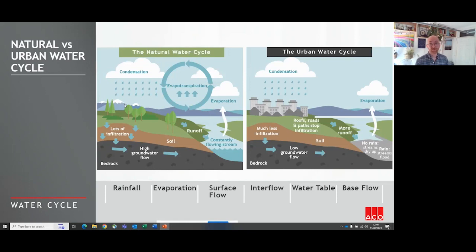Then from the drainage system, it either goes to the combined sewer. Then because the drainage system can't handle it, because it's clean water, then essentially they discharge dirty water through these controlled units that go straight into the watercourse. Now, the problem is that over a period of time with increased urbanisation, you don't get that pore water flow through the ground strata, and therefore the riverbeds and everything dry up through evaporation because the water just doesn't survive for a long period of time through the summer months. So having that infiltration to the ground is really important.